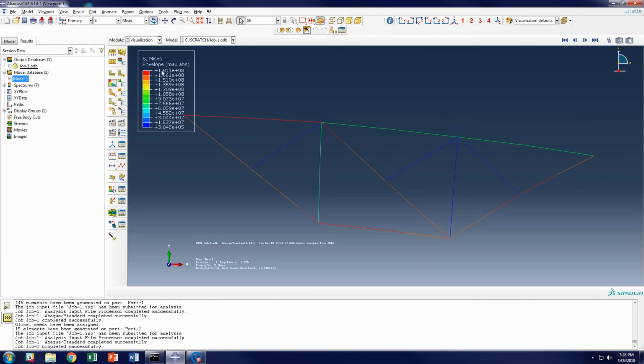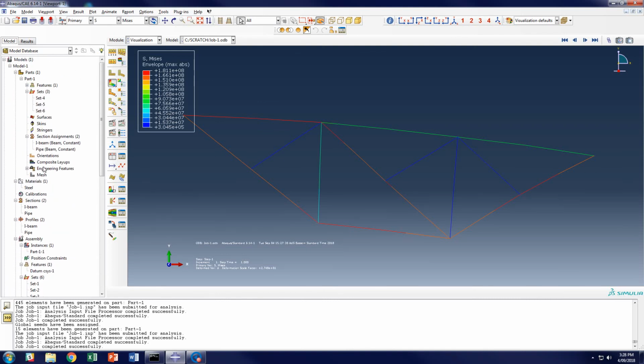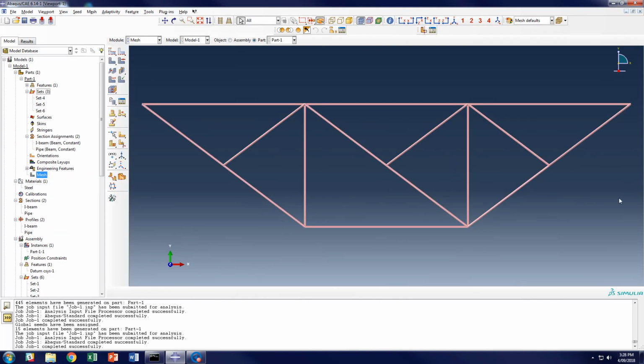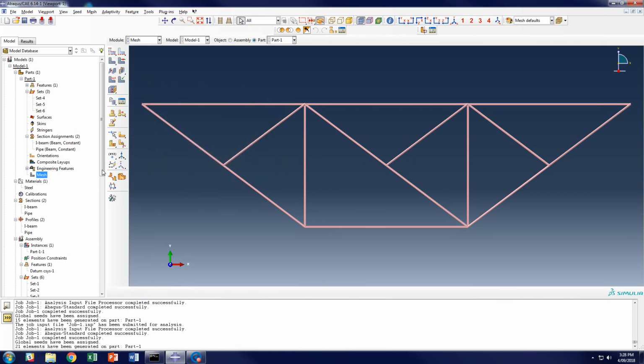All right, and now the stress is immediately back to what we were looking at before. So we're looking at 181.1 megapascals, so that's a difference of 0.2 megapascals between the 445 elements for linear beam elements versus the 15 elements for a quadratic formulation. Now we still need to demonstrate that the result is independent of the number of elements. So we might change that down to a 4 mesh size, and we might remesh it.